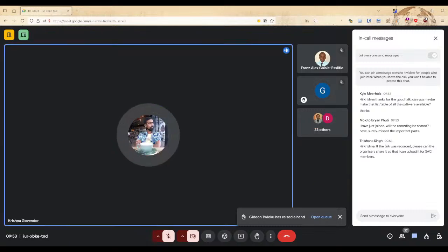Okay, thank you very much, Edward. So even if you're using something like Gromacs, the same thing applies. You can basically break your simulation up into blocks, right? Because remember, in your Gromacs input file, you specify how many nanoseconds you actually want to achieve. So that's the part where you would keep the time step the same, but the total simulation length is what you make less.